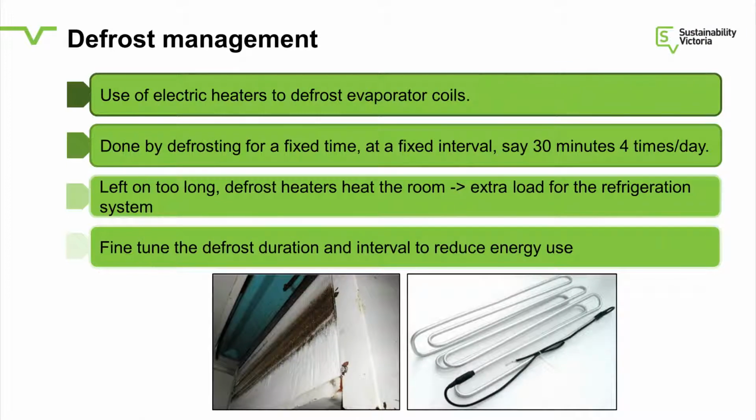So defrost. Remember the early slide where a big chunk of the energy was used by the defrost heater? We have to use defrost heaters when it's a freezer, because we have to put heat into it. Even if you turn the refrigeration off, the ice is not going to go away. And even with most cool rooms which run below 4 degrees, you still have to use electric heaters to defrost. If your room runs at 10 degrees, you can do what we call off-cycle defrost. You can just turn the unit off and the heat in the air will eventually cause the ice to melt. But for most cool rooms and freezer rooms, you have to actually have an electric defrost heater.